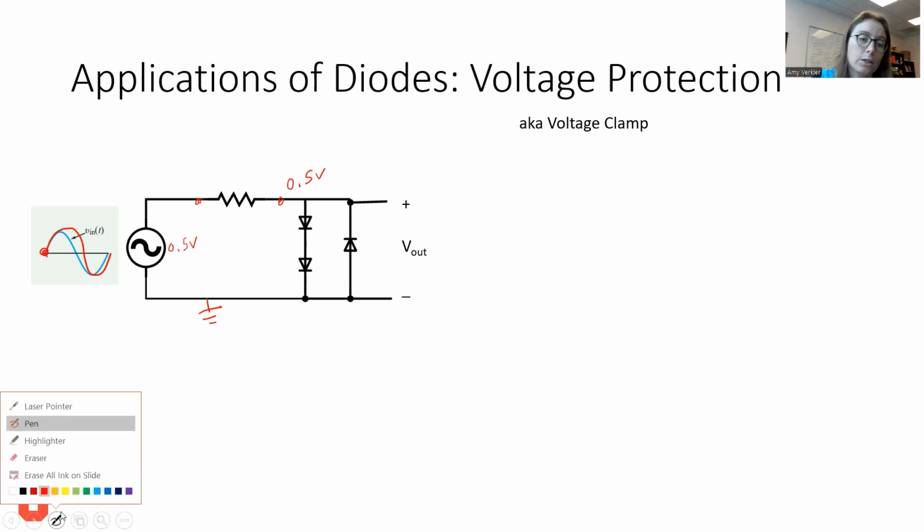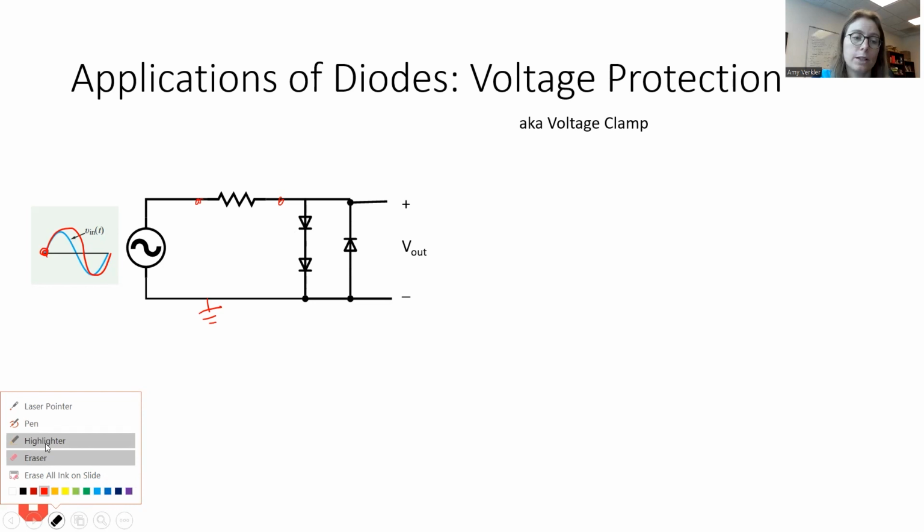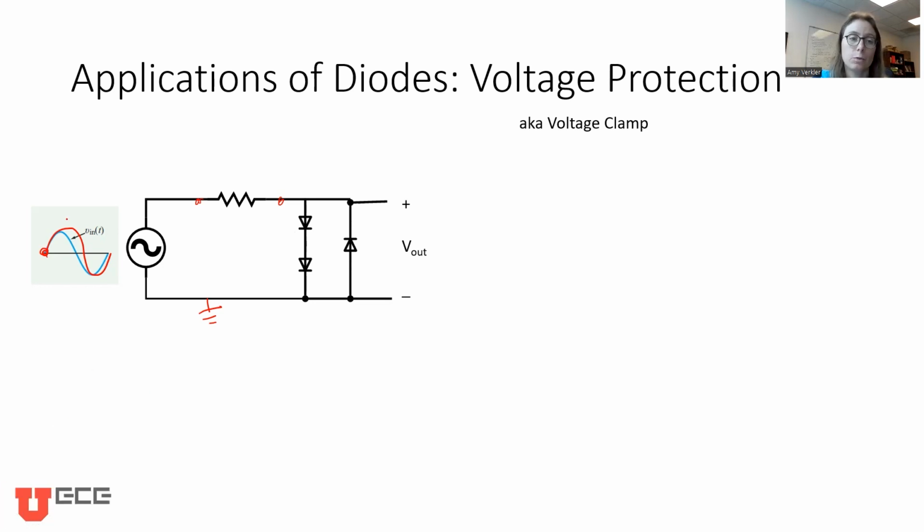Okay, so now let's go look at a different case. What if we get those two diodes in series turned on? So let's say we have 2 volts now. We're up here and we're at 2 volts. So if this is 2 volts, that's more than the forward voltage of each of these combined, because 0.7 plus 0.7 is 1.4.